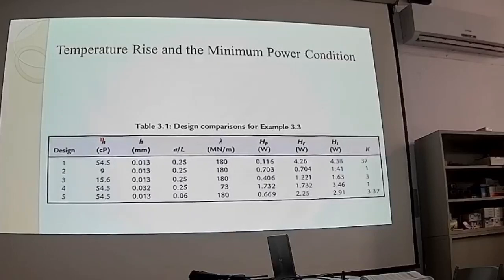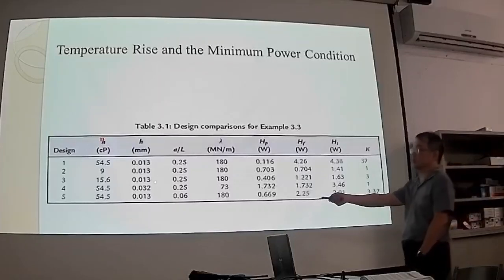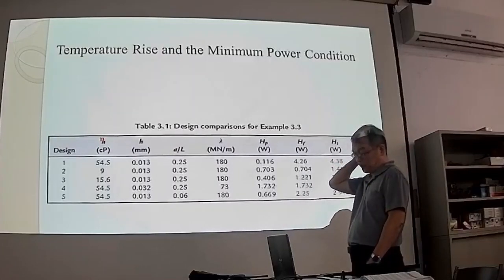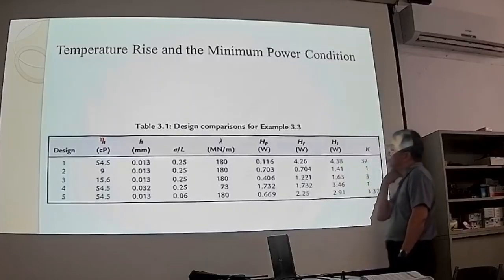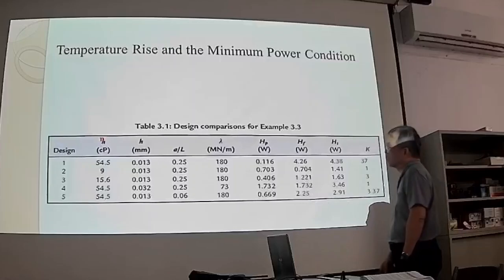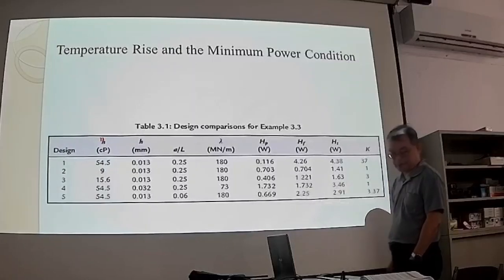So normally we will not change the clearance. The film gap thickness is very critical to the bearing performance. You can change the other parameters.